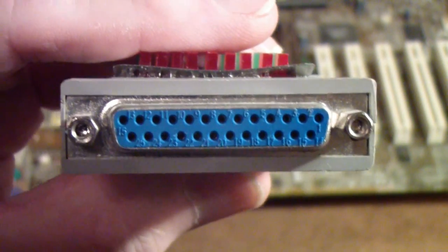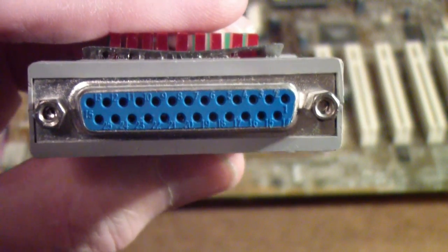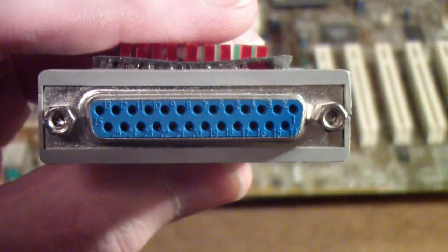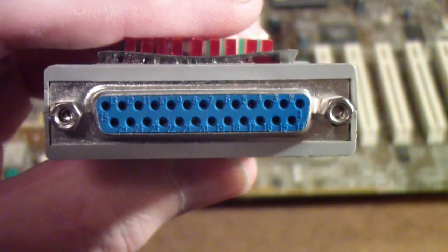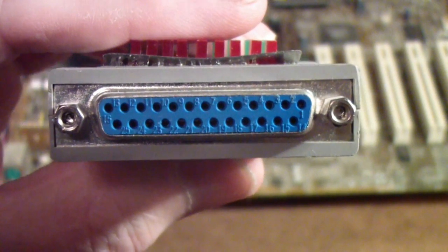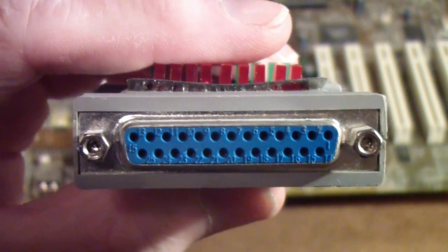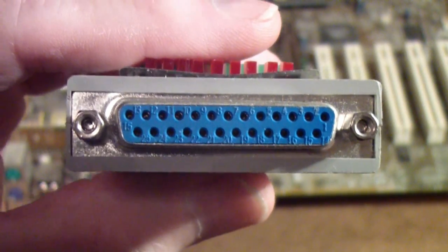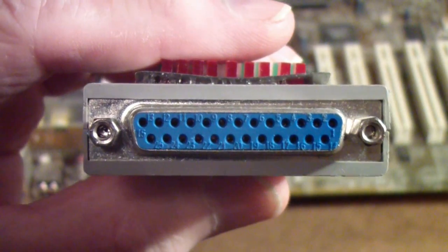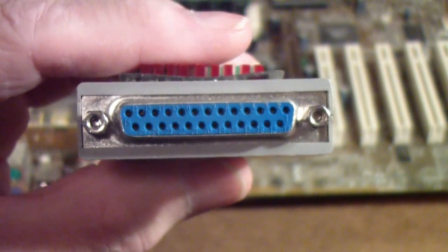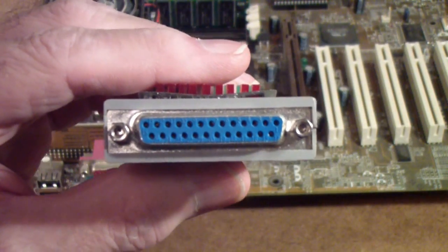But the basic standard was bipolar, that is, it would swing between positive and negative to generate the marks and spaces of the old teletype. And it converted from a current loop interface to a voltage interface. Now, over the years, the UART invented at DEC, and the RS-232 standard, developed by the Electronic Industries Association,